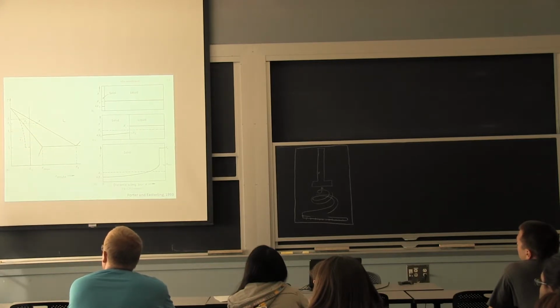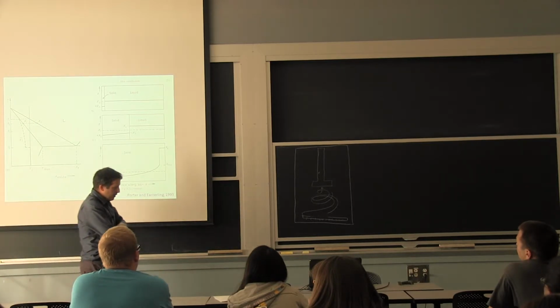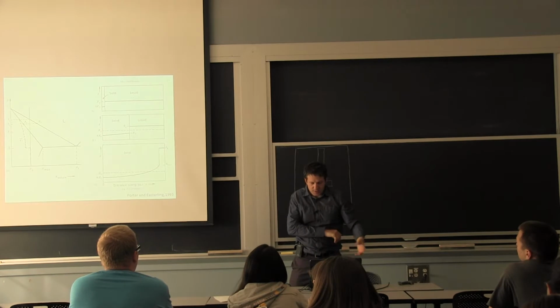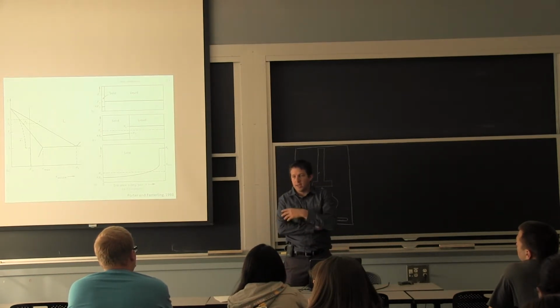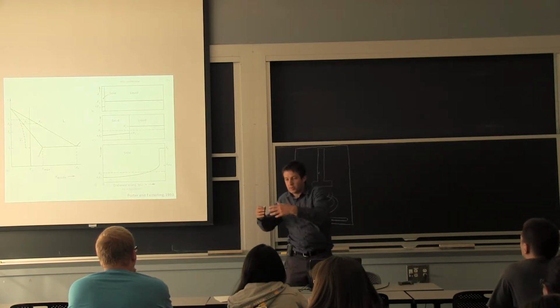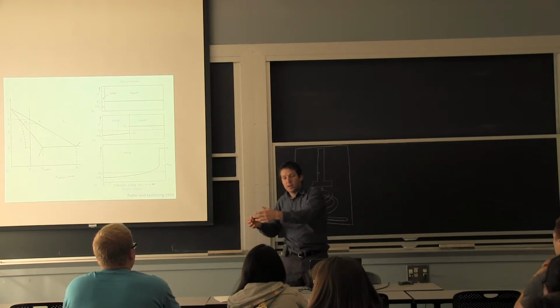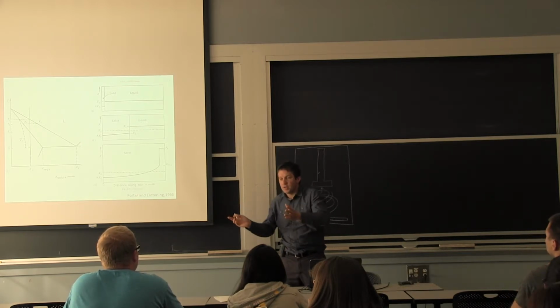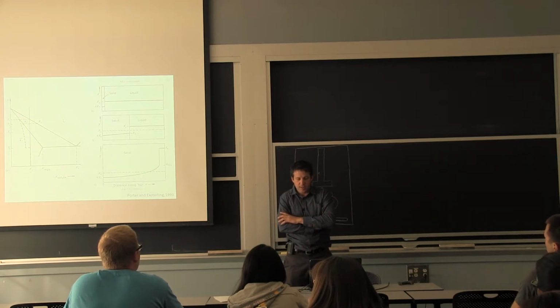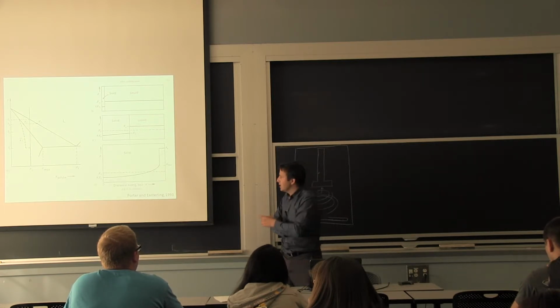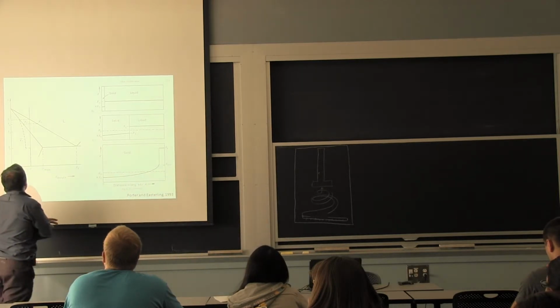And that's where we talked about the diffusion and essentially taking the alloying elements and pushing them forward from the solidification front. And that's where I started talking about, well, it's easy to form dendrites then, because you're sort of accumulating things right ahead, and then you want to side branch it and find other ways to solidify that are more favorable in terms of kinetics.